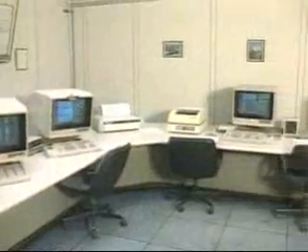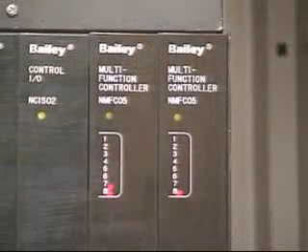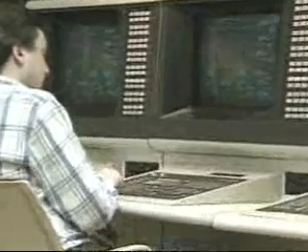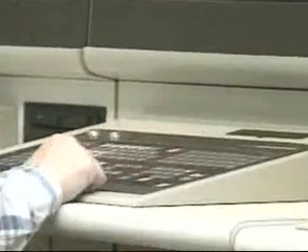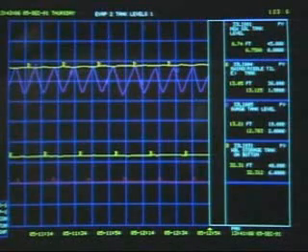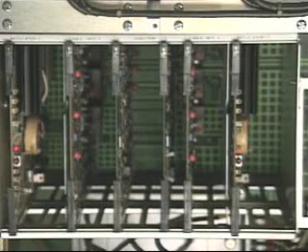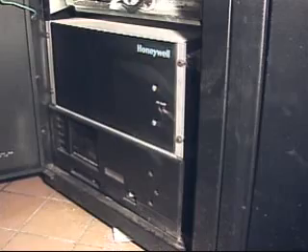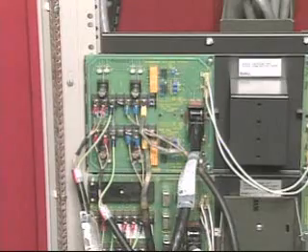Although there are several different types of distributed control systems, they have some similar major components. For instance, in addition to the controllers we just talked about, there are operator consoles. Operator consoles have keyboards that allow operators to send commands and data to the rest of the system. They also have displays that give operators information about the system. Network equipment, such as this traffic director, manages the flow of data on the system's communication network. Memory devices supplement the memory capacity of the computers and the process controllers. And communication interfaces connect the equipment in the system to the network.